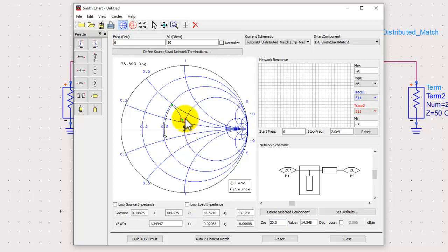And if you wanted to reach the same point, let's say at similar location, now we only need 12-degree instead of 35-degree. So immediately you have 1/3 of space saving in your overall circuit design in terms of the length of this stub, right? So the key fundamentals to take away here, wherever you need inductive behavior during transmission line matching, increase the impedance of the line to let it behave more like inductive as far as you can go. And wherever you need capacitive action, try to reduce the impedance. That means make wider line in your PCBs to get more capacitive action.